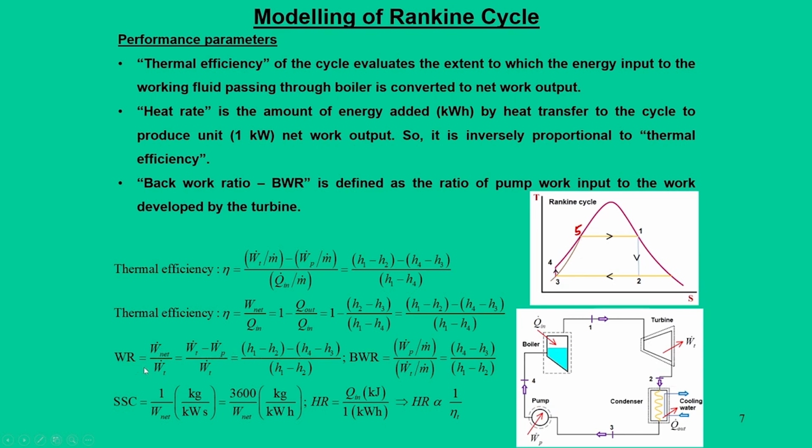The other interpretation of work ratio is the back work ratio. Many books interpret it as back work, that is pump work to the turbine work. So, both have the same meaning. Ideally speaking, our work ratio should be higher, or the back work ratio should be as small as possible. The other important aspects are specific steam consumption, measured in kg per kilowatt hour, and heat rate, that is nothing but the Q input per kilowatt hour.